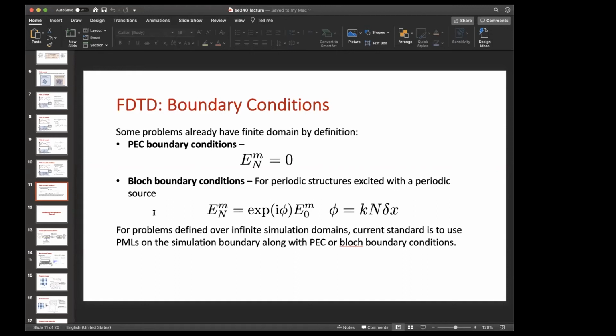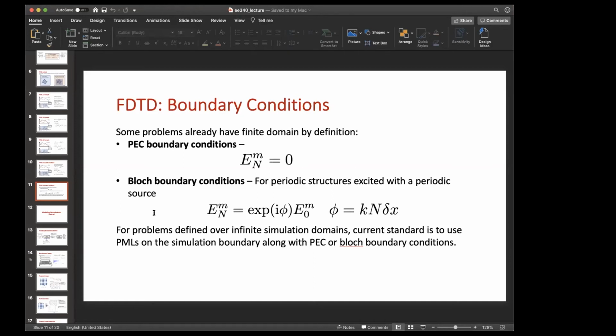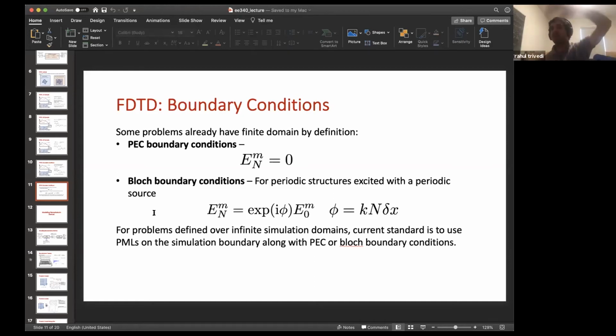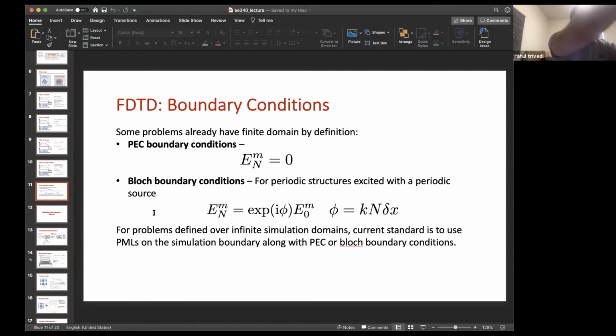For the example you just mentioned, can you truncate in time before it reaches the very far PEC boundary? You could, if that's your interest, yes. Okay. So if you take a very far away PEC boundary, until the fields start interacting with your PEC boundary, you'll actually have accurate simulation, right? Yeah, but keep in mind that you need to load all of this into your computer memory, right? So it's impractical for sure.